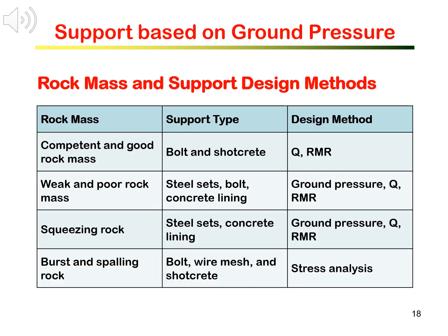This is the end of sessions on rock support design and underground excavations in rocks. Here is a summary of support design methods for different rock masses and support types. Again, as we mentioned earlier, for support of hard rock and generally competent rocks, empirical design using Q and RMR have proven to be very well suited.